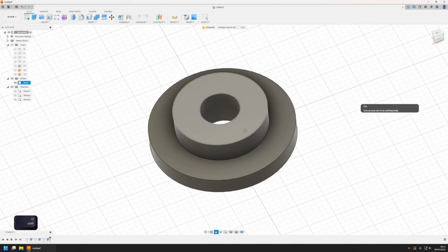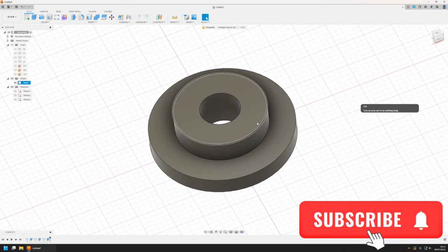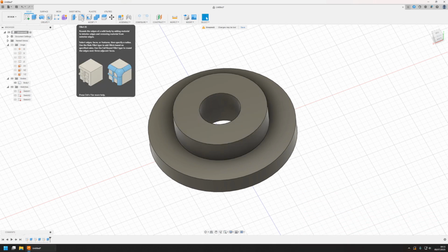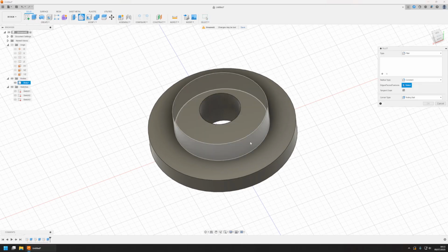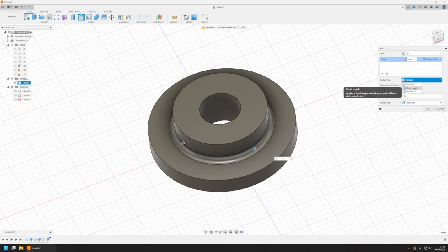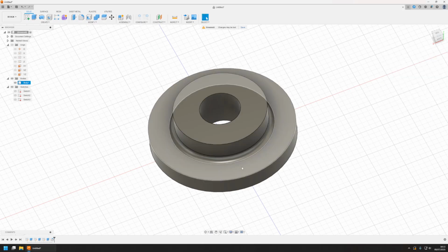Okay, now we need to take care of the chamfers on these radii, or rather edges. We go to fillet. We will add a fillet as well. Let's start with the fillet. We have this radius here, which is a fillet, 5 millimeters. You have some options here as well. You can have it constant, you can select the chord length instead of the radius, and we can have a variable. But here we're not going to be worrying about that. We just use a constant 5 millimeter thickness.